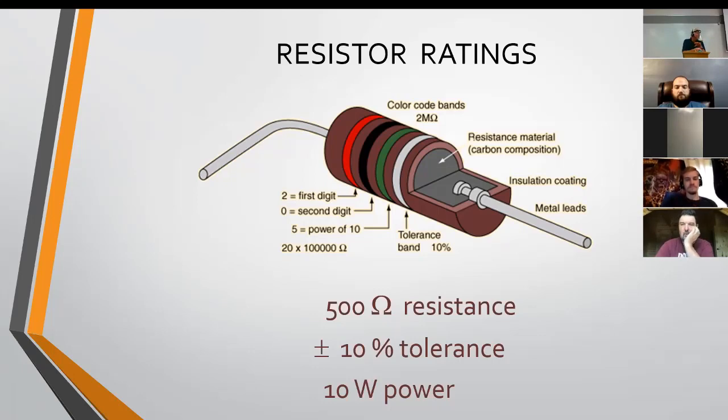But also there's this issue of tolerance, because when you have something like a 1K resistor, that 1K is nominal. We call it 1K, but it's like you call a 2x4 a 2x4, but if you actually measure it, it's not. Or 3/4 inch pipe, that's its nominal size, that's what we name it, but if you actually measure it, it's not. And so we have a 1K resistor, but if you measure it, it may not be. It may be plus or minus. And so that's the tolerance. How much plus or minus away from its nominal rating is it?